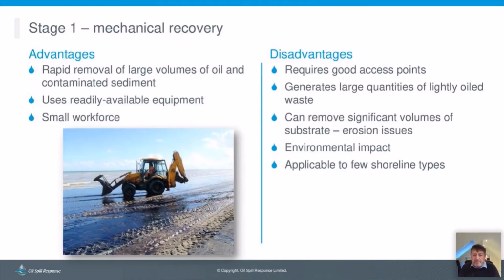Potentially it could have more of an environmental impact, so it's something that needs to be very carefully managed. What you don't want is machinery driving over an oiled shoreline, pushing the oil further into the sediment. Or driving off an oiled shoreline and taking contamination further down the road or into the local residential area, for instance. And you can only use it on a few shoreline types, really. It's got to be quite a flat shoreline type, like a sandy beach or maybe a gravel beach.